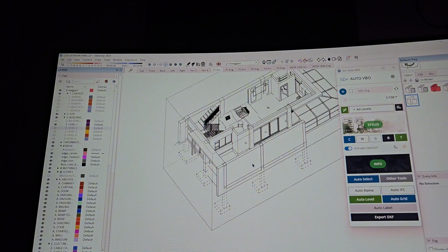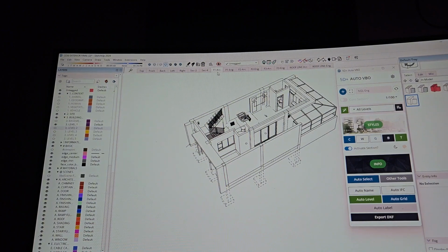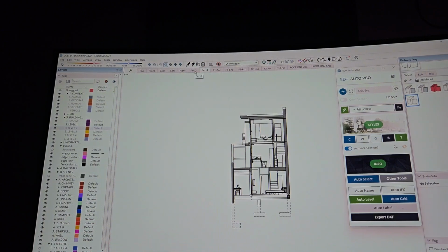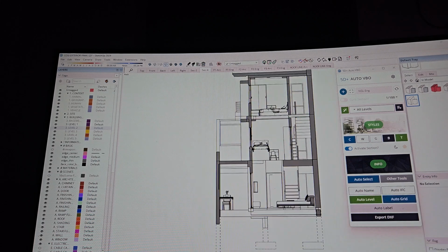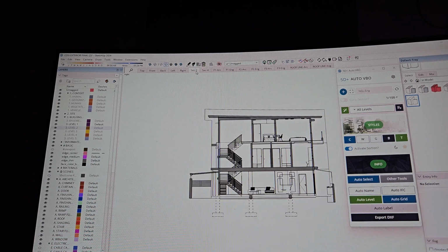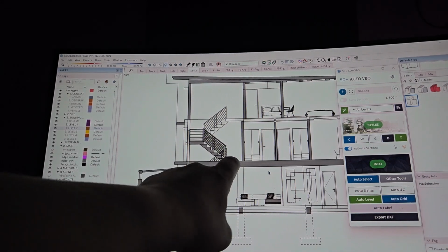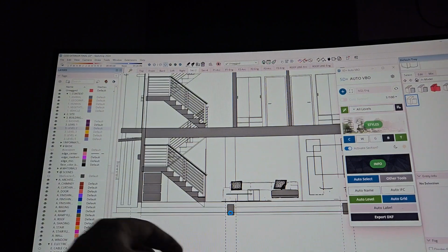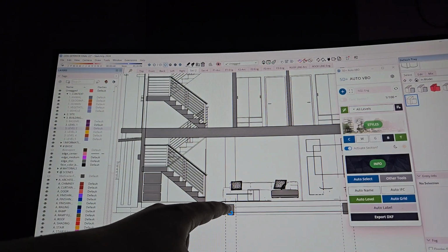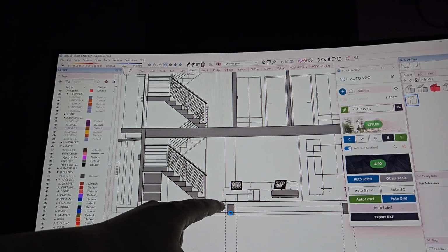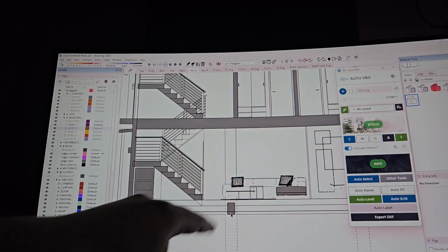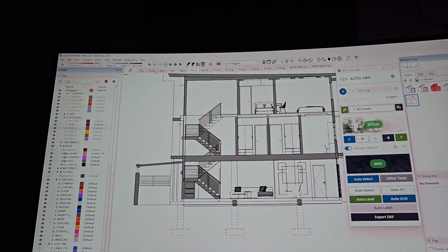So if you continue doing that, you will get something in a section that shows the beam and the columns. So you'll have beams here like this we have right now. This is the top of the beam, right? The grade beam. And this is the finished floor line, or the floor finish line. That's why we have that earlier in our front elevation.